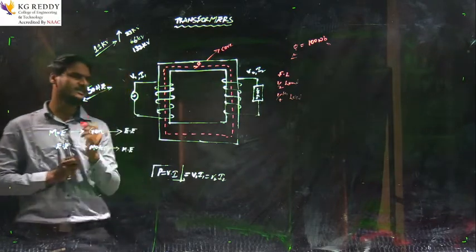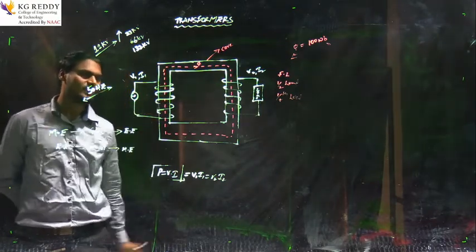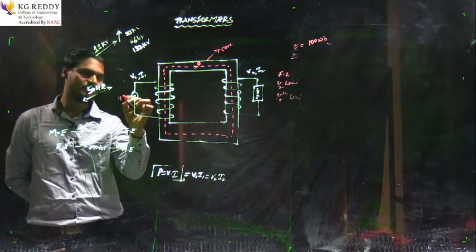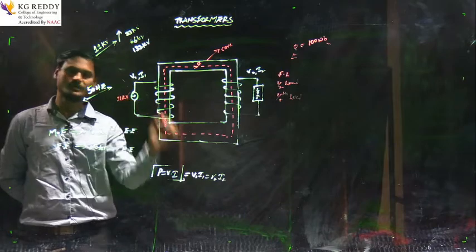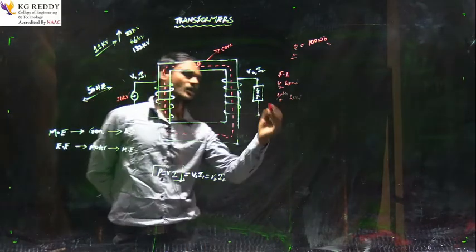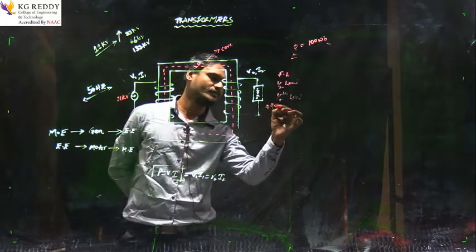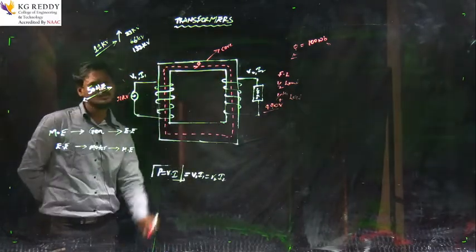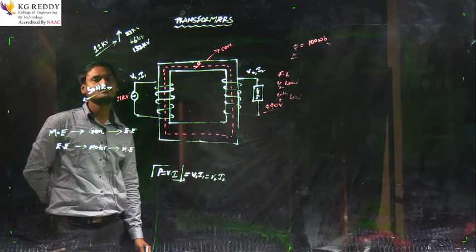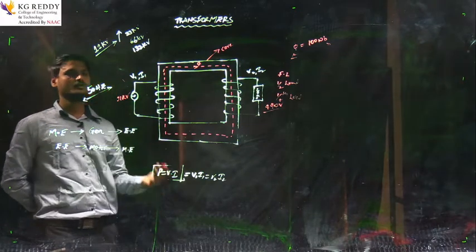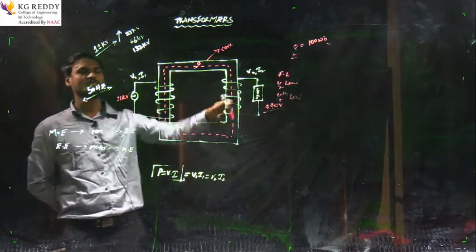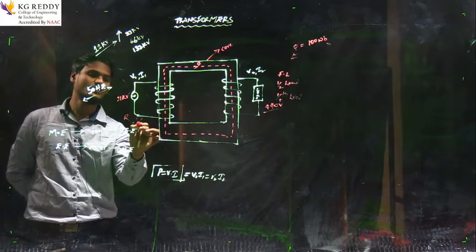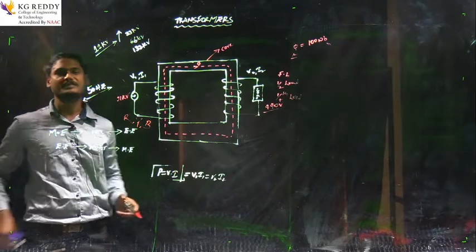Now you can see here, guys, for example, it is 11 kV that I am giving here, and the load will be 440 volts for 3 phase, not for single phase. Just I am drawing here a single phase circuit, but coming to 3 phase, there will be 3 windings. Why? Because there should be the R phase, Y phase and B phase.